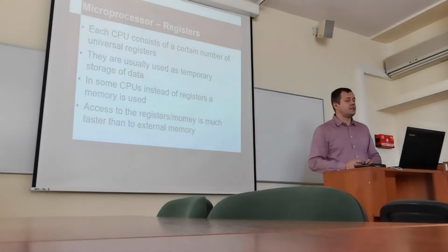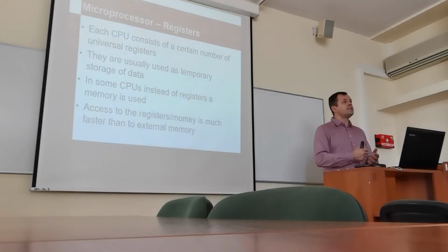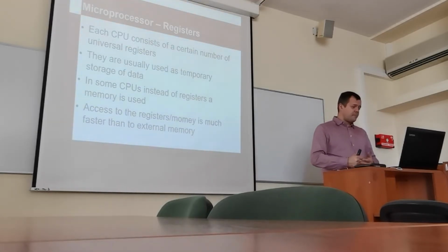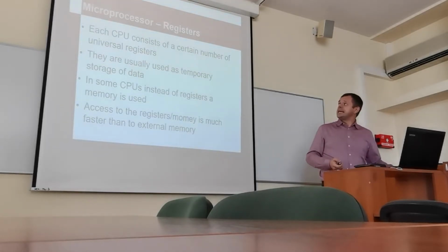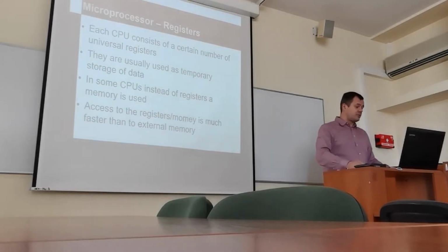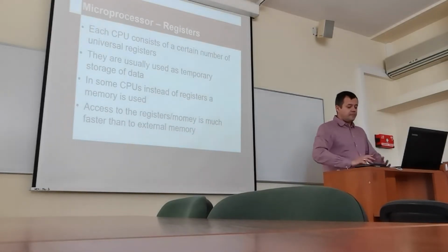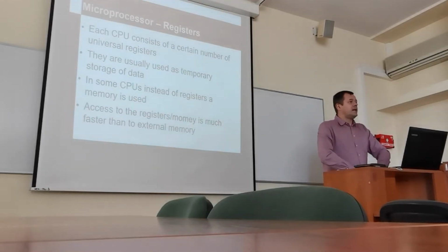So the instruction decoder and arithmetic logic unit must have a program counter, program stack, registers, and the fourth auxiliary element is the interrupts and the interrupt controller, because the interrupt controller is usually external to the microprocessor. But in general, the idea of interrupts and the support for interrupts is a very important element of each microprocessor today, and it's almost impossible to use a microprocessor effectively without an interrupt.